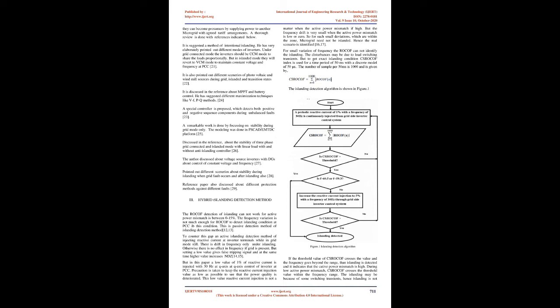The active islanding method injects a small reactive current, disturbing system parameters like voltage and frequency. When the grid is available, these disturbances are taken care of. But in its absence, care is to be taken of the stability of the microgrid [5, 6]. The passive RCOF technique cannot sense if the deviations are below 15% active power at PCC. Hence an active islanding detection of small reactive current injection at inverter terminals is used, so that the power quality is not disturbed. This is a hybrid technique which combines both passive RCOF and active reactive current injection.